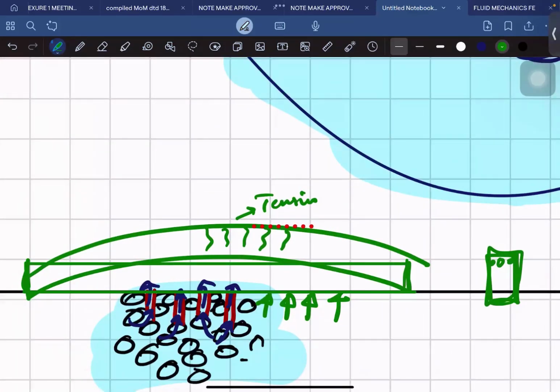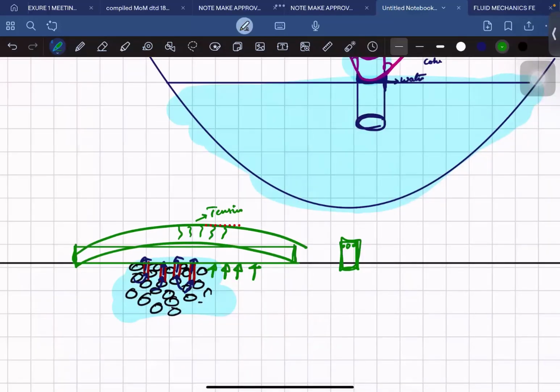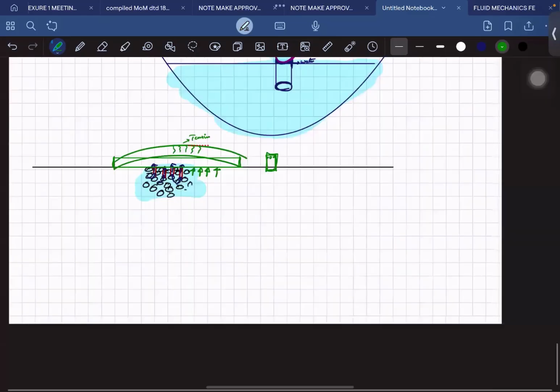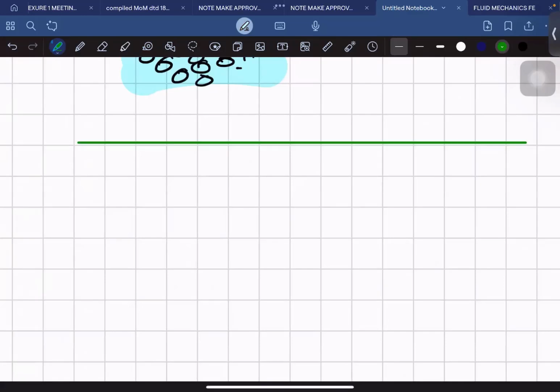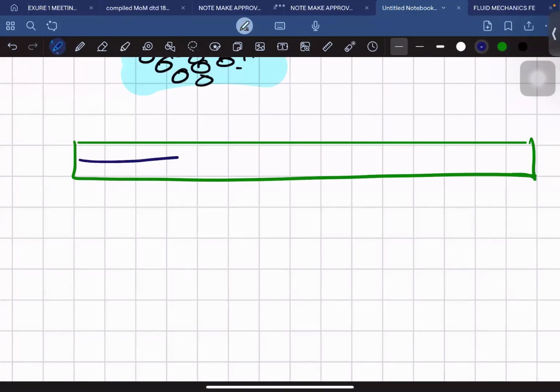Even when you take the grade slab, what is grade slab in structural civil engineering? Grade slab is nothing but the slab on which the floor lies, right? On the earth, we'll pour a grade slab. I'm just giving you one practical example. If you work at site, in the grade slab, the tensile reinforcement is not given at the bottom, it is given at the center.